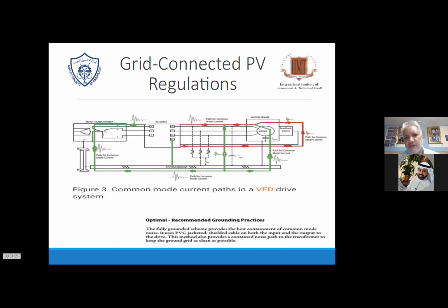And all of a sudden, after 4 years, the modules degraded. I was called out, and they wanted to replace half or 30% of the modules to see what's going on. Then I checked the inverters and the leakage current, and I saw that the leakage current in the water pipes and the grounding was tremendously high.